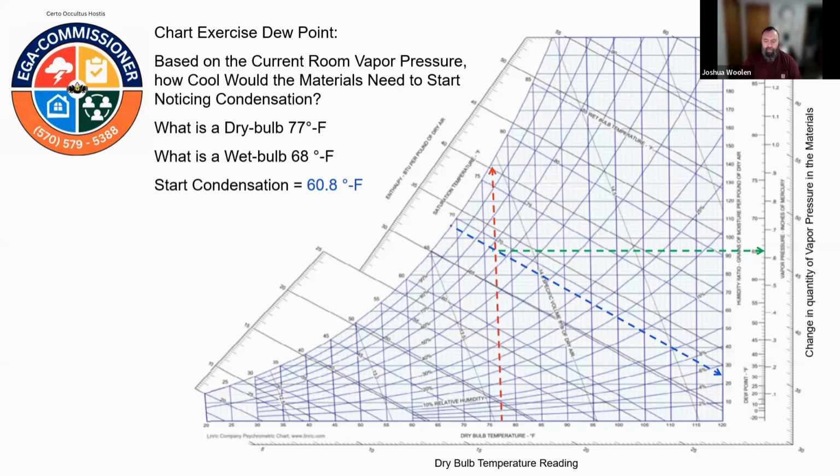And while you're doing that, you also can go to your dehumidifier and confirm your dehumidifiers are working to expectations by understanding the grains per pound, right? So that is another part that we need to understand when we're talking about vapor pressure and the driving forces behind all that moisture phase change.